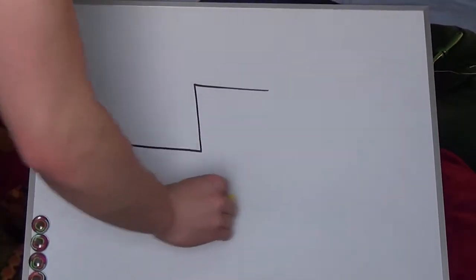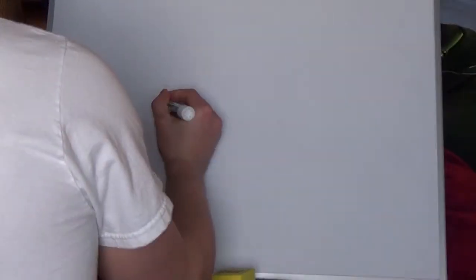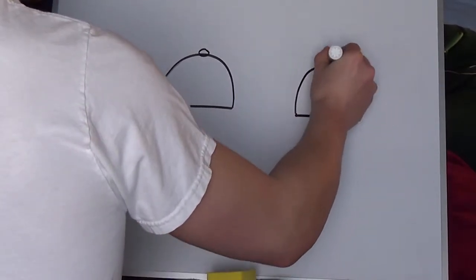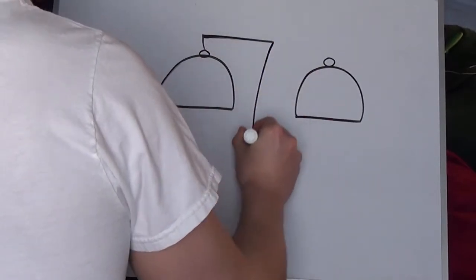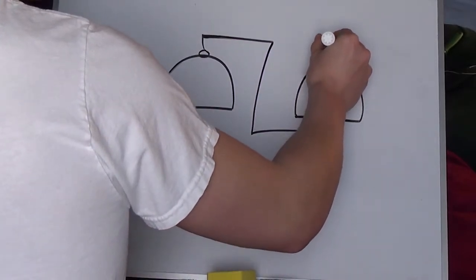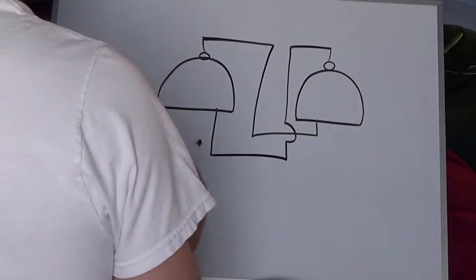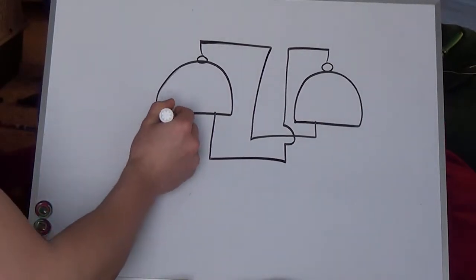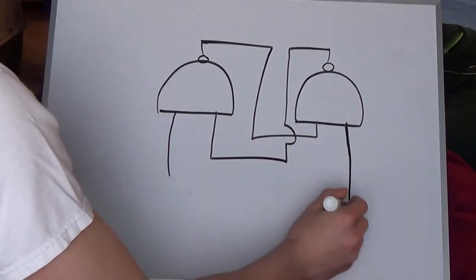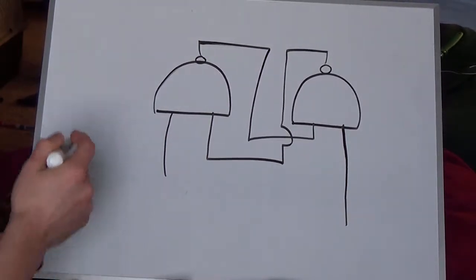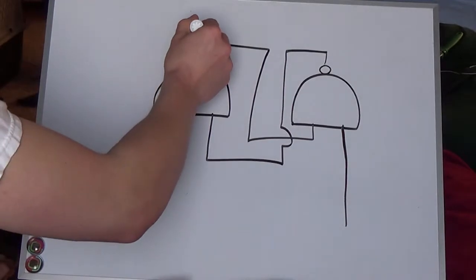So in order to solve that problem, I just used an SR NAND latch, which we talked about in the previous tutorial. I'm using an SR NAND latch for, I don't know what you call it, debouncing maybe, but I'm basically smoothing out that signal. To remove all the oscillations from the signal, I'm going to use this Q as my output.